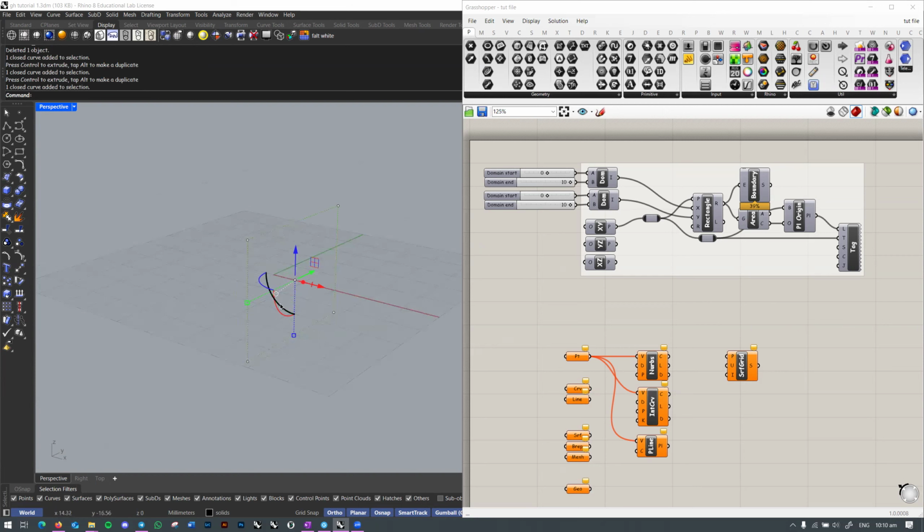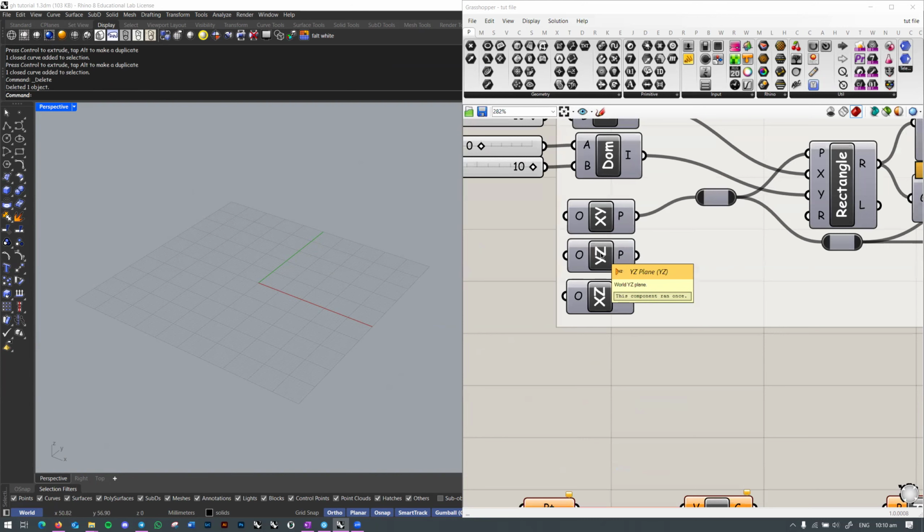These are just the default planes. You can also draw rectangles on a slant like this, or even a double angle slant like this. So all this depends on what plane you want the computer to work on, right? For the sake of simplicity, let's keep it to the three world planes, which are the XY plane, the YZ plane, and the XZ plane.